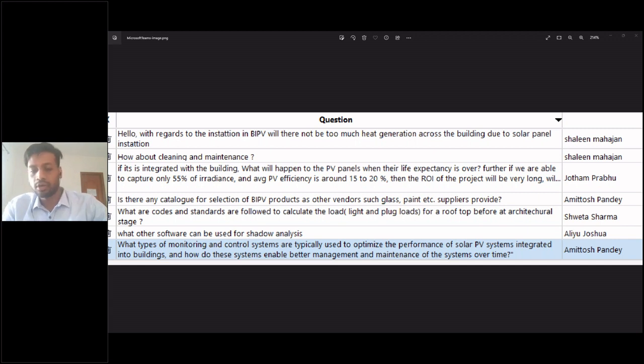If you're not going with the facade structure installation and you're considering only the cost of BIPV installation, then your statement is true, but that's not the case. We are using an offsetting mechanism. You're going to be spending whatever the capital investment is on a normal facade structure. We are increasing that cost by 20 to 25%, but we'll be generating energy with that increased cost. So the ROI will not be really long.